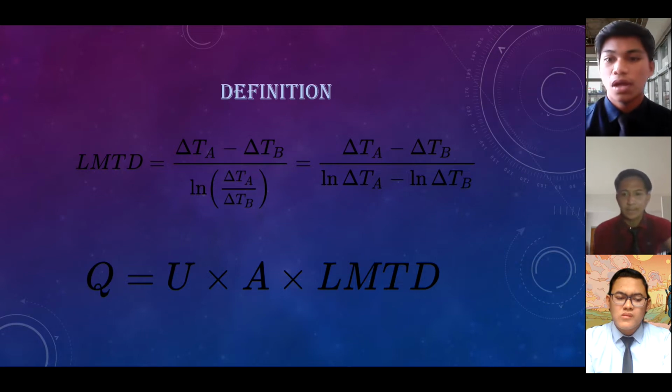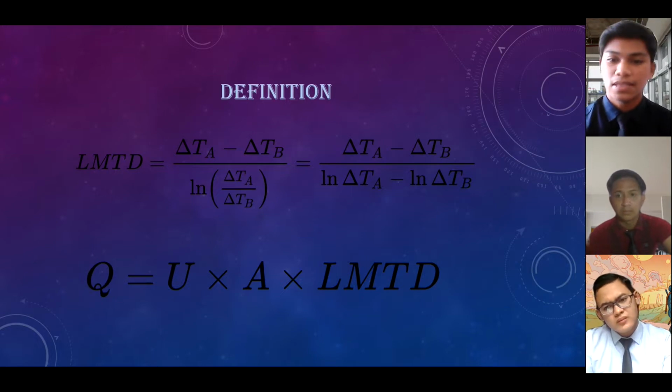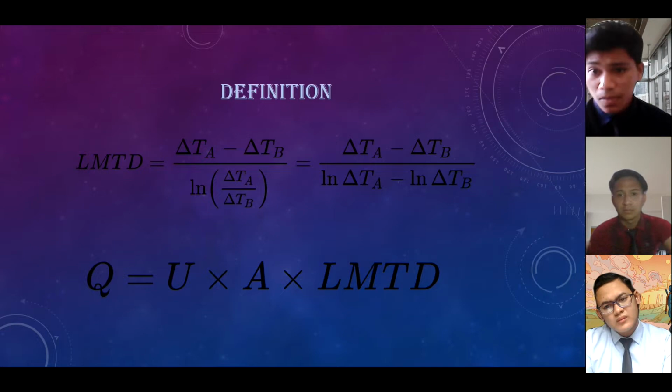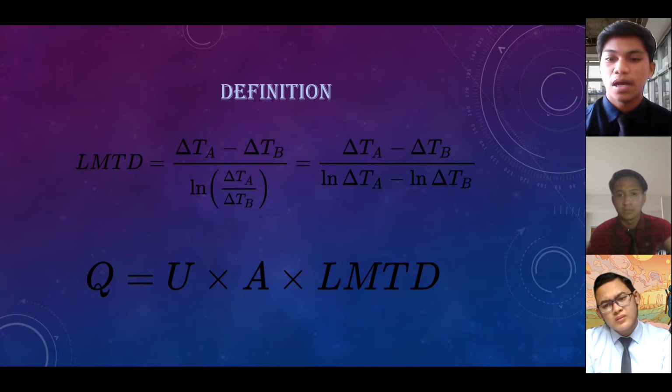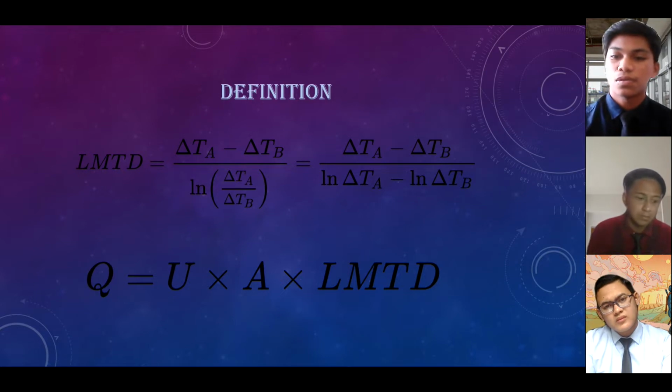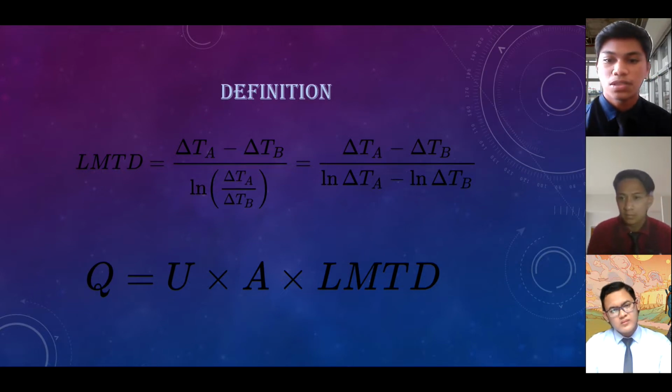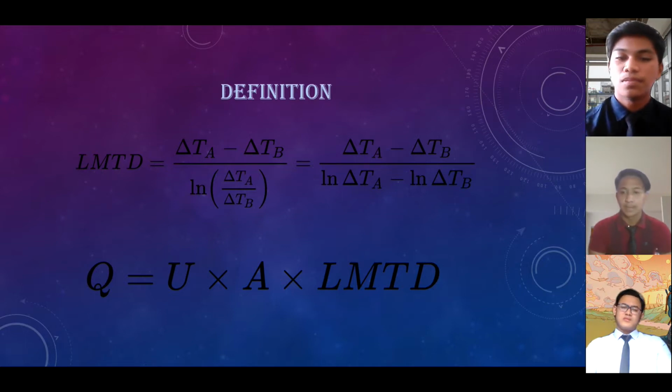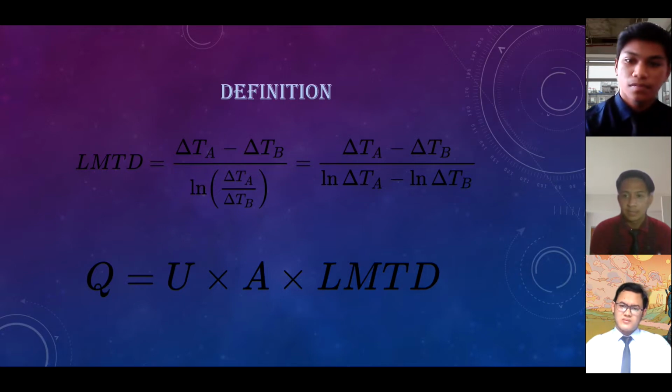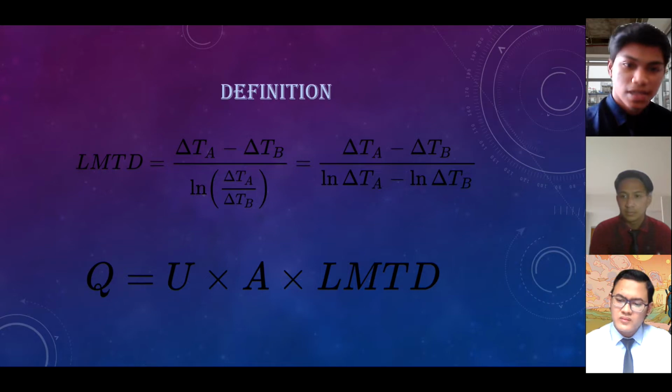In a cross flow, which is one system, usually the heat sink has the same nominal temperature at all points on the heat transfer surface. A similar relation between exchanged heat and LMTD holds, but with a correction factor. A correction factor is also required for other more complex geometries, such as a shell and tube exchanger with multiple passes. Okay, next slide.